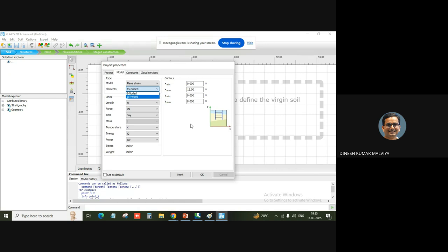After that, we need to define the contour of the soil domain. While considering the contour, you need to have an idea about the boundary conditions involved. Most of the time, in layman's terms, if a raft or shallow foundation is there, the influence of that particular foundation is up to 5 times its width. Influence means the involved stress zone, the settlement contours and those things. So when you are doing any type of finite element modeling, you need to define your contours very wisely.